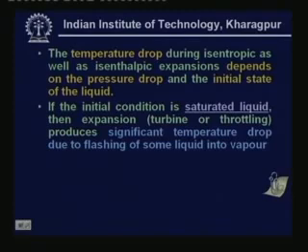If the initial condition is saturated liquid, then expansion, whether using a turbine or a throttling device, produces a significant temperature drop due to flashing of some liquid into vapor. Okay, so let me explain this one.